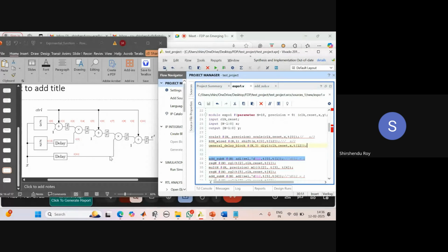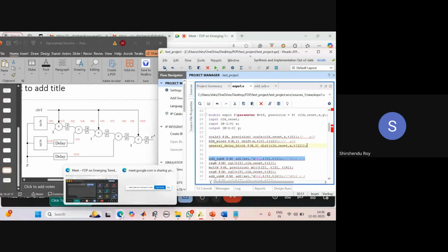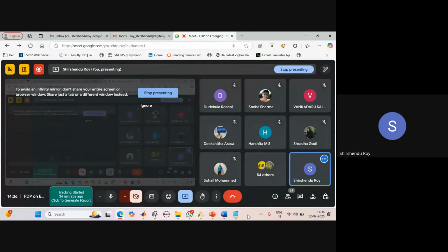So can you calculate the delay here? What delay it should be? If you see, you can easily calculate that up to this multiplier, we have 3 delays. After this, we have one register and another register placed here. Total delays, can anyone tell what is the amount of delay we should place for this X? Anyone? It's very important to have the same delay for each signal.